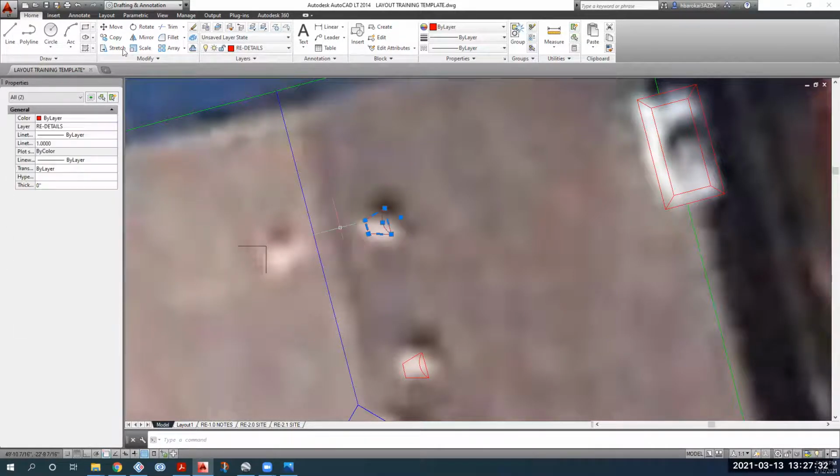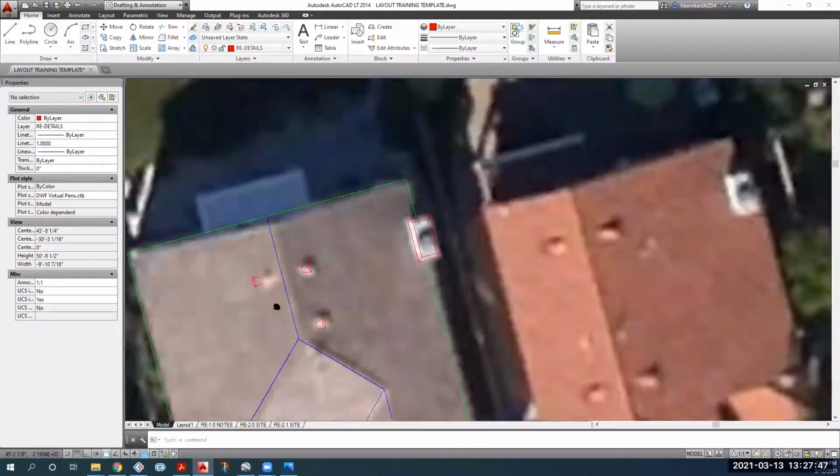So instead of just rotating it, I can just mirror it with this center line. I'll show you guys how to mirror things again. Basically you select them, you go to the mirror command, and then you select the line on which you want to mirror it by selecting the endpoints, and then click and press enter. So that's how it mirrors things.